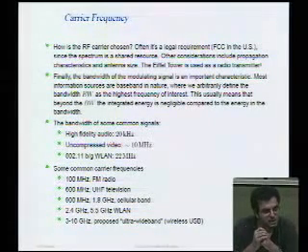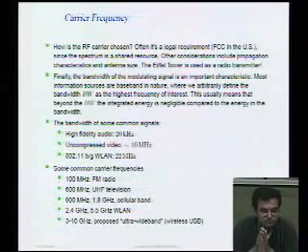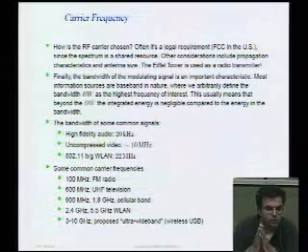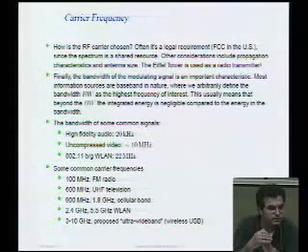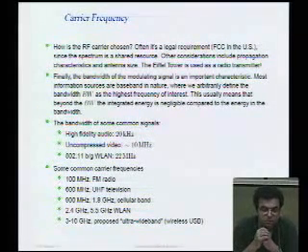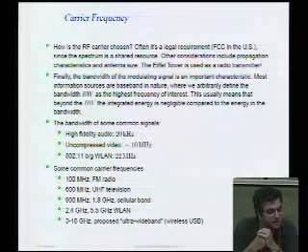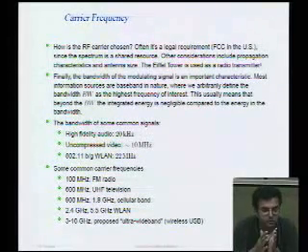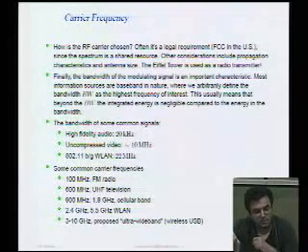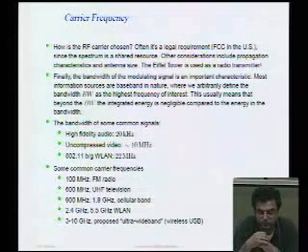That's a very small fraction of the bandwidth. So I could, let's say, allocate frequency from 1 gigahertz to 1.01 gigahertz and have a bunch of channels in there. But if now I want to transmit, let's say, high-speed data, let's say wireless LAN, then I may need 10 megahertz of bandwidth or 50 megahertz of bandwidth. And so then the number of channels that I can use goes down. So generally, the higher the data rate, the higher the frequency, because you can have more channels.